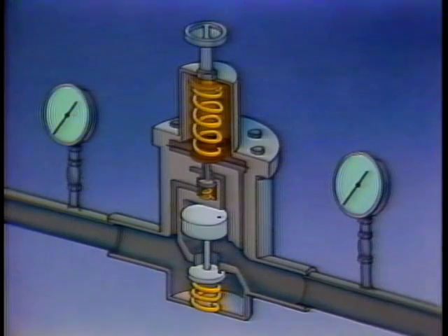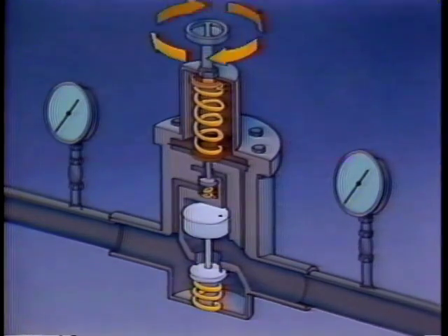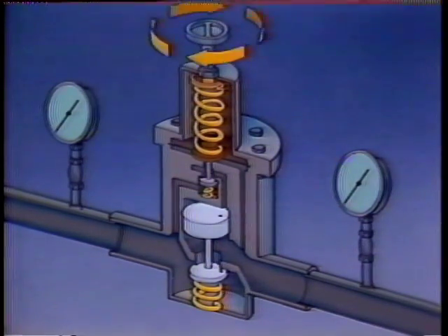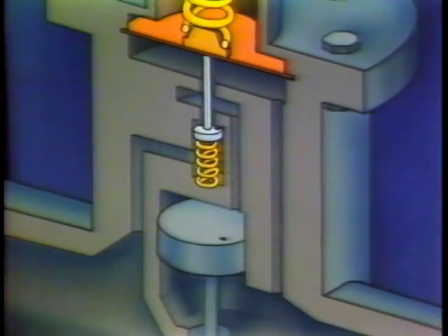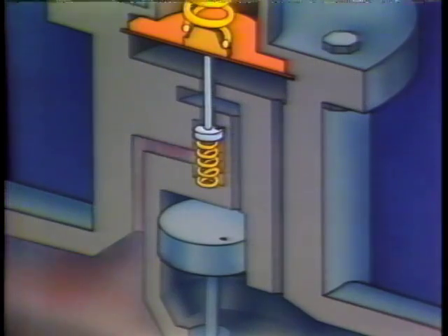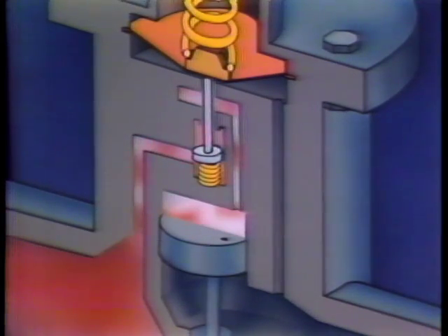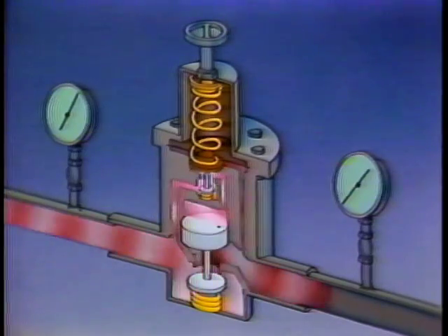Here's how pilot-operated PRVs work. By increasing the force of the set point apparatus, inlet pressure on the small pilot valve is overcome. A small movement in the metal diaphragm pushes open the short travel pilot valve from its seat, and inlet pressure flows to the top of the piston, opening the main valve.